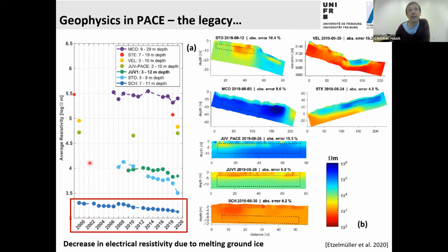That was to characterize the site and to decide where the borehole should be. From this time onwards, there was one site which we tried to continue measuring every year. That was a bit explorative in the beginning, because we were not sure whether by measuring every year we would get a thawing signal strong enough in terms of electrical resistivity. But it proved to be the case.